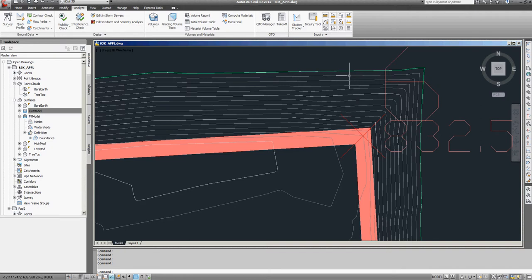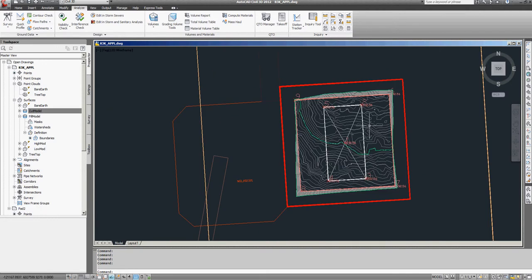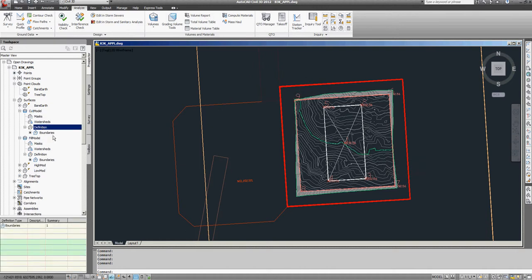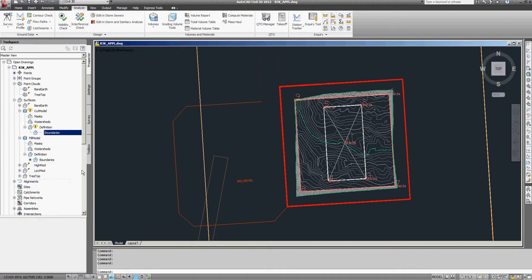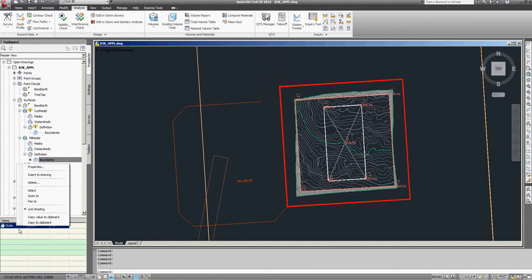On this side, the edge of the lease is sitting on top of 1.39 meters of fill, going down to 0 where it meets here. And then you have your map across the entire lease. One of the interesting things then, of course, is if we decided that we wanted to, for example, have more cut material because we wish to transport some material for borrow somewhere else, or for example to pad up an access road or such, it doesn't take us very long to, for example, drop the entire lease and recalculate these contours.